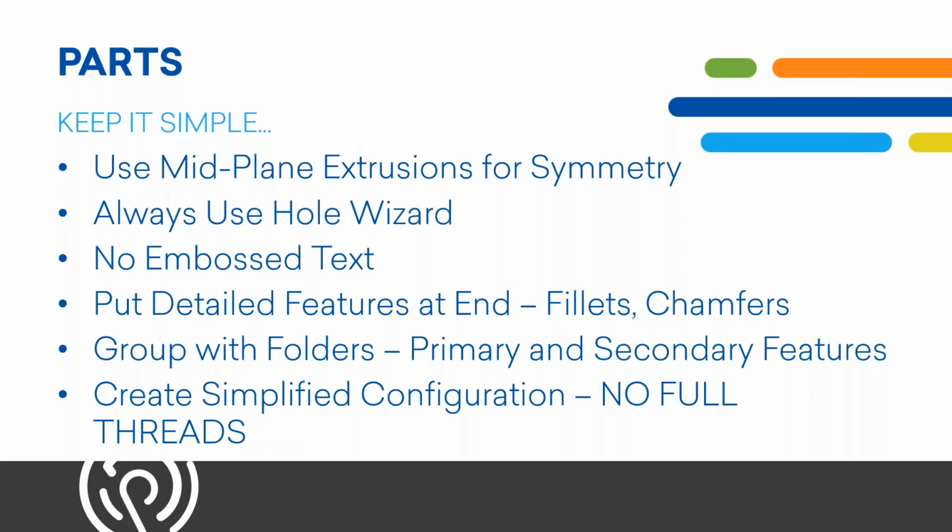You'll see the sketch and you'll see the cue that you need, but you won't have the extra faces that you have to work with relative to a model and the graphical processor. Another way to do that would be to do a split line instead of embossing or actually raising the text. I will talk about that when we get to the practical example, which is shortly.